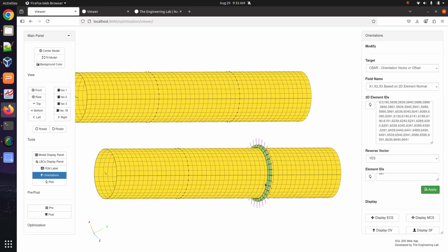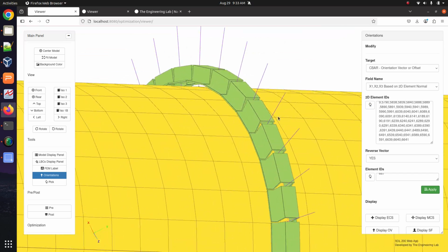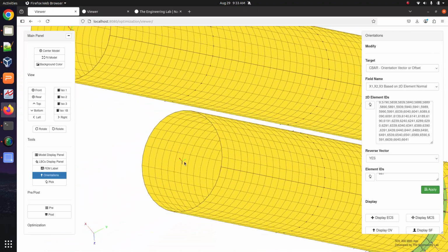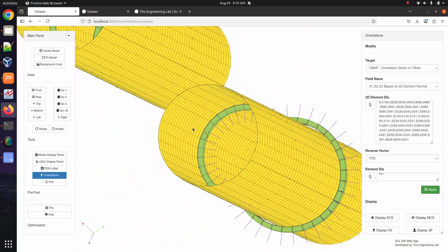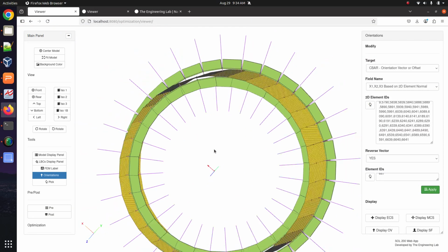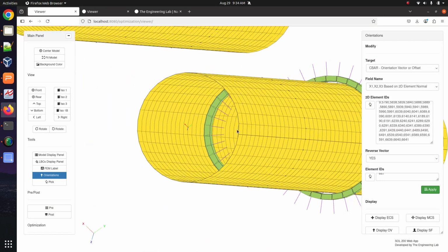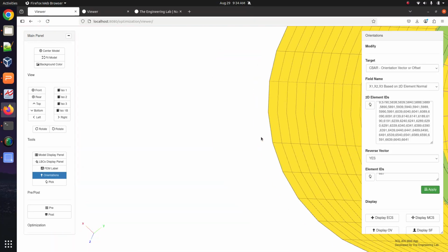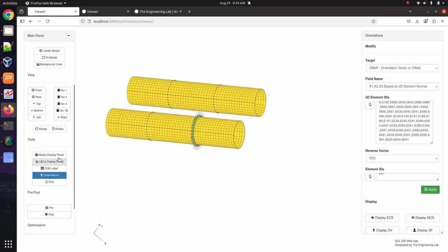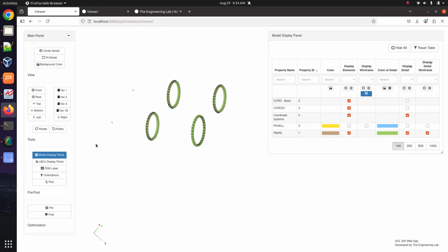So you can see that the original orientation vectors for these elements are unchanged. They were not modified in this action. But we said use the reverse of the orientation vector. So these other beam elements, the orientation vector is now reversed, like you see here on the screen. If we look at those cross sections, you can see that. Let me hide the wall for now.